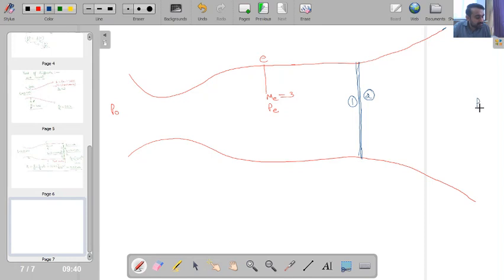In this case, this is my P infinity equal to 1 atmosphere. Another important point is that here I have a normal shock wave, so on the downstream of the shock wave I will have a subsonic situation. So M2 will be less than 1. As M2 is less than 1 and I have a diverging duct, what ultimately will happen? This is subsonic flow through a diverging section, so there will be a further decrease in Mach number and a gain of pressure in the duct section.